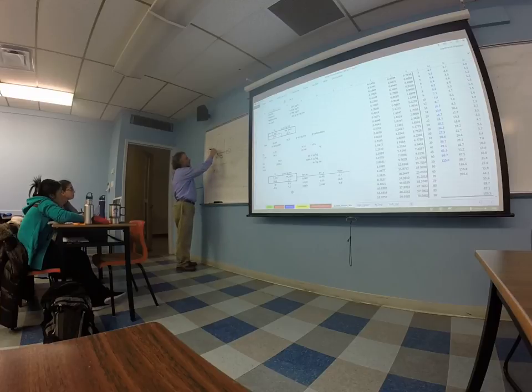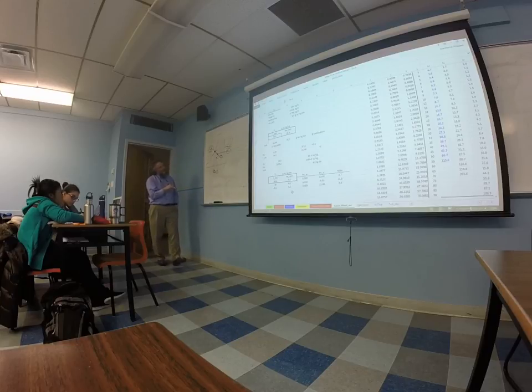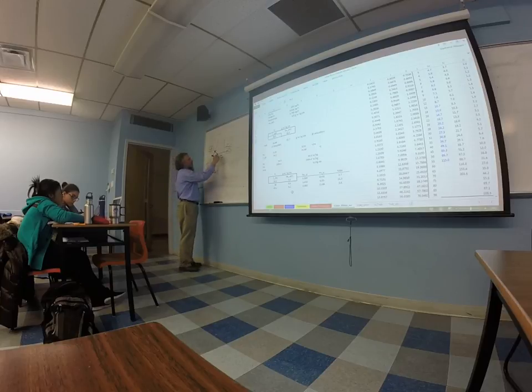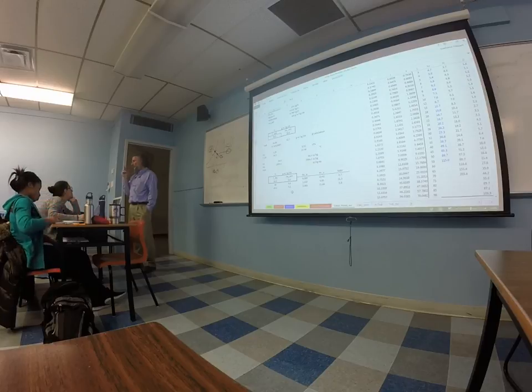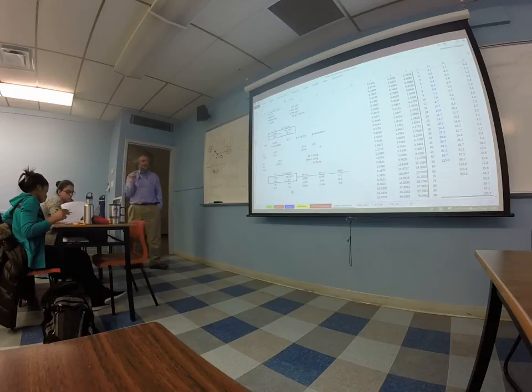So with my definition of enthalpy, there's going to be another moisture content here at saturation, at another temperature of saturation, that's going to give me a temperature. And this temperature of saturation is the same as the wet bulb temperature. So I calculate this enthalpy first, with the data that I have: a moisture content and temperature. Those are the only two pieces of information I need to calculate enthalpy.